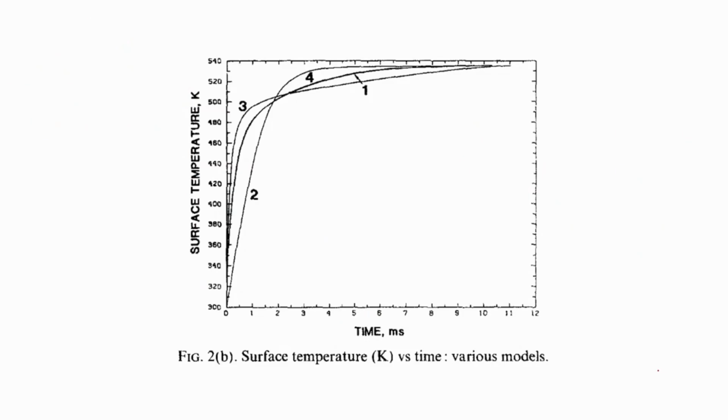let us look at the surface temperature, on the other hand, based on the different types of models that we have over here. Now, if you look at the surface temperature, once again 1 and 4 you should recall: 1 is the vortex or the extended model, 4 is the effective conductivity model, effective K model. So, once again you see 1 and 4 are very close to each other. 2 shows that kind of a profile, 3 shows that kind of a profile.